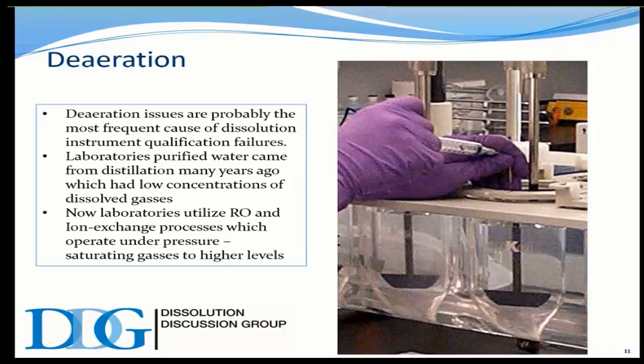The second, enhanced mechanical qualification, does not have a section on deaeration of media, but as recommended by that guidance from FDA in 2010, laboratories since 2010 have been required to have procedures in place to control significant sources of variability, primarily of which dissolution could come from degassing methods. They have to be validated. They have to be tested on a product-by-product basis for new drugs under development.